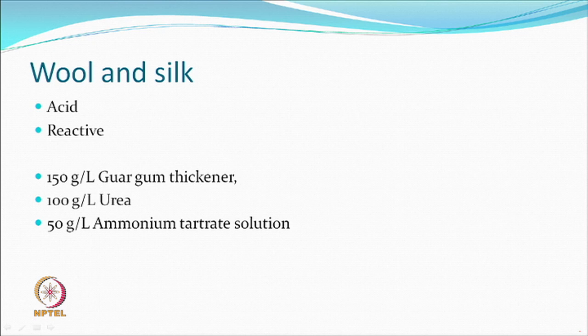If you do the acid, you will obviously not use alginic acid or alginate, because in the acidic environment it coagulates and you can have difficulty. So, one of the interesting thickeners that remains is guar gum, which is okay. You do control molecular weights in a manner that during washing later you should not have difficulty.